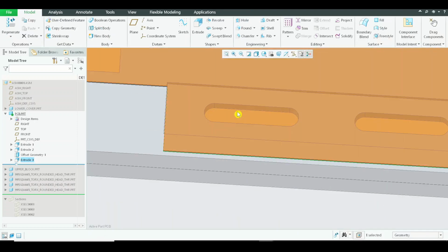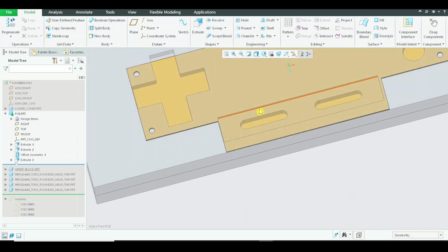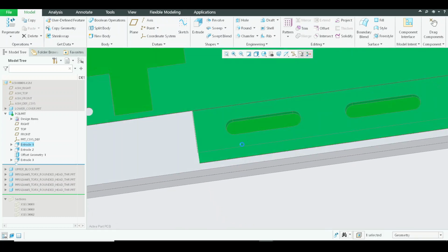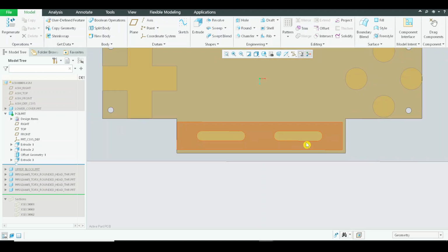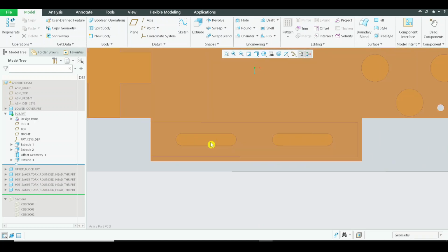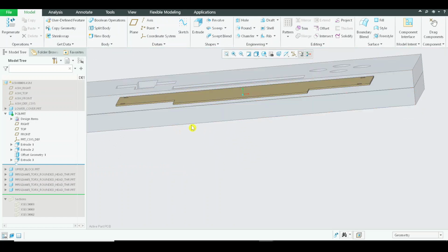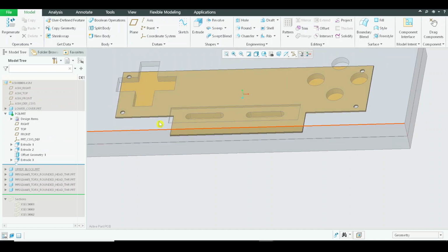Right, now imagine if technically an electronic engineer who is aware of this PCB knowledge says that you cannot extend the board like this and have your circuit board created, then never mind, you can just add another set of bosses and place this PCB board. Nevertheless, we require another set of bosses on the left and right, because you can see that if this button is placed, it will have a deflection as it moves downward, right? So we require 2 additional bosses for support, which we will be doing right now.